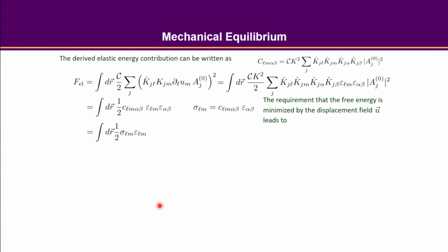And in the amplitude equation, in a sense, the free energy is a function of the amplitude and also the displacement, or the strain. And since we know the system is always going to bring the energy toward the minima, I can also take a functional derivative with respect to the displacement, and I expect the energy to be minimized.